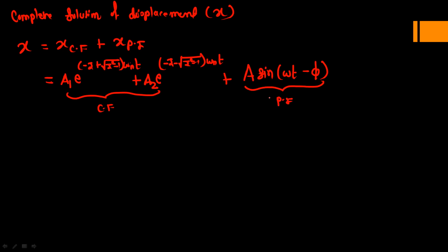So this is just a mathematical equation. But what is the physical significance of this equation? So how can we visualize the actual waveform during forced vibration? Therefore we should refer to the displacement time graph from the damped vibration, because this complementary function is the same equation as the damped vibration. Okay. So just consider in this equation zeta, which is a damping ratio, not coefficient, it is a damping ratio. So zeta is greater than 1. So this case is an overdamped system.